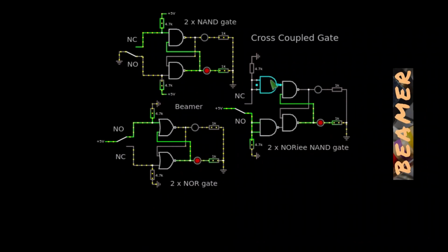I've effectively used the other 2 NAND gates as inverters, but this could be an inverter from another package. And as you can see, the input resistor to this inverter is a pull down implementation, with the wiper being at plus volts. So the whole of this circuit is identical to the twin NOR gate cross-coupled implementation, and it works exactly the same way. And that's it. The next thing I'll do now is demonstrate this back on the bench.